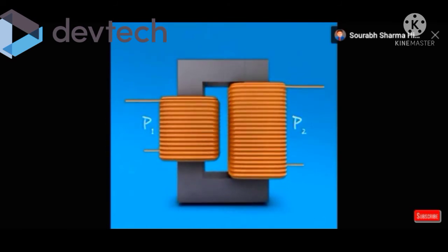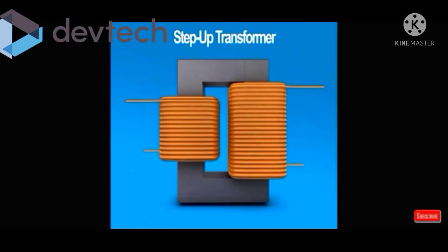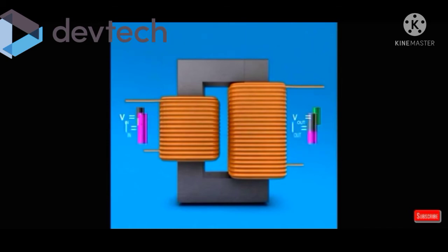As you can see here, in this case the coil on the left side, which we can call the primary coil, has a lesser number of turns than the coil on the right side, which we can call the secondary coil. And the transformer is called a step-up transformer. In this case, the voltage induced on the secondary coil, V out, is higher than the voltage applied, V in, on the primary coil, whereas the current is reduced as the power has to remain constant.